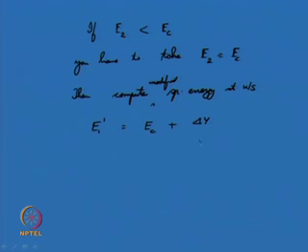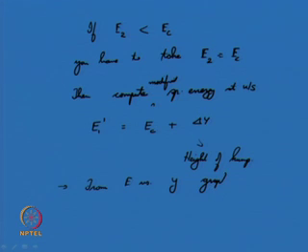Del y is the height of hump. So, once you compute E1 dash from E versus y graph, find modified depth y1 dash at section 1.